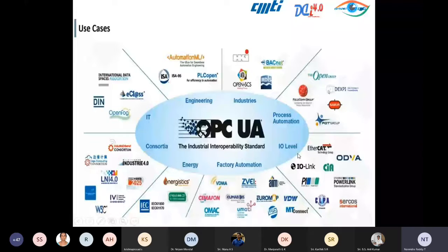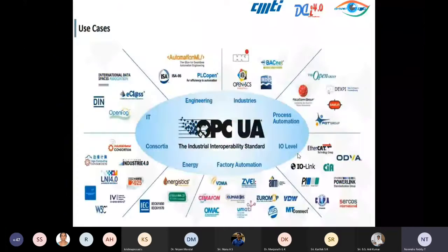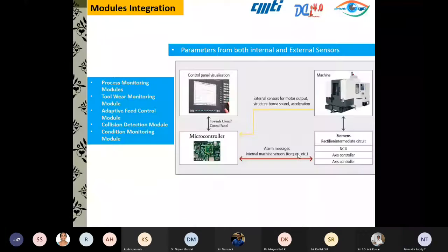With this introduction to machine connectivity completed, I will go to machine connectivity applications. What are the applications? I said it is mainly for metal cutting, and I will limit my presentation to metal cutting. You have a CNC machine. The CNC machine will have a CNC controller. It could be a Siemens, Fanuc, or Mitsubishi. Now with the help of OPC or MTConnect. I think for Siemens it is OPC. For others, you have to use a different protocol.